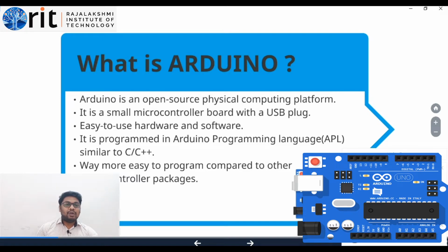And if you are going to directly interface with existing controllers like the PIC16F877A, which is a mid-range family of PIC microcontrollers, or Motorola microcontrollers, or ARM based microcontrollers, we should know the basic architecture in order to do something on the board. But if you are using Arduino, there is no need to learn the basic architecture. You just go through the basic layout and interface some components, and using the Arduino IDE software you can code it and the prototype is ready for use. This is the beauty of Arduino.